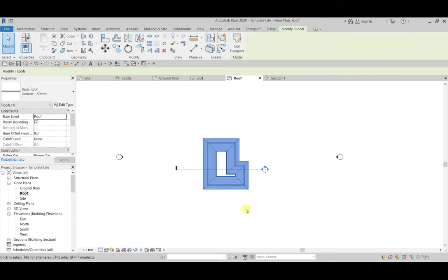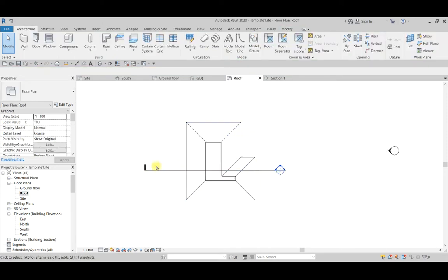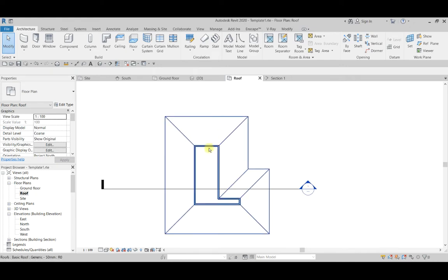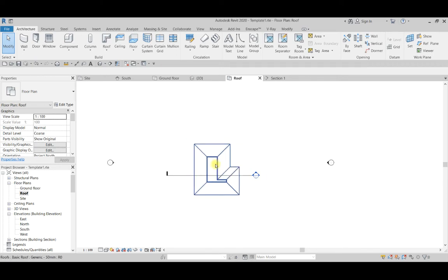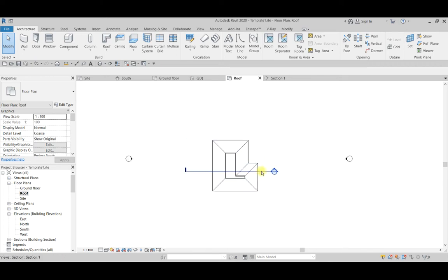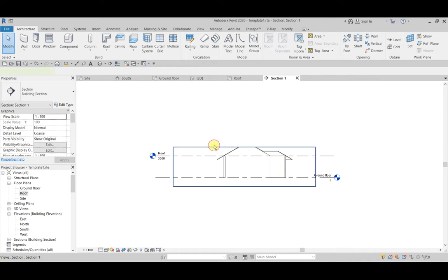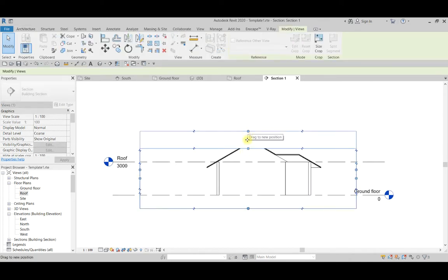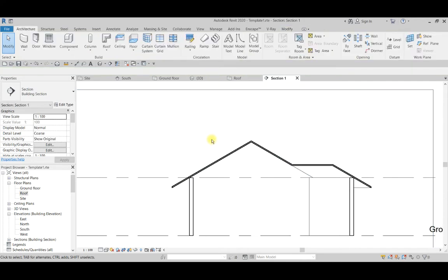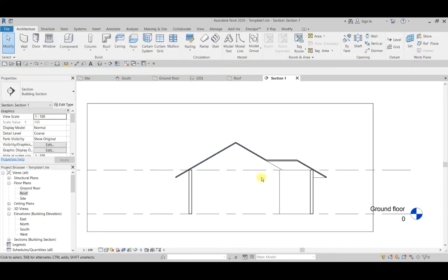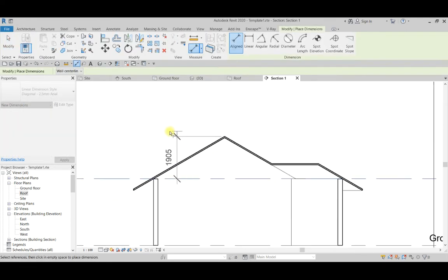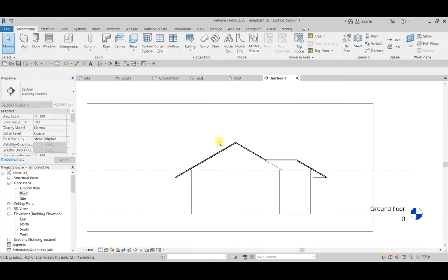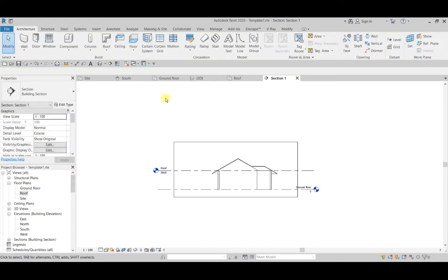on OK. So realize that the view range in which we are having has made a section through our roof, and we are not seeing the apex of the roof. So I'm going to give you an example to see how it works. So when I come here, before we can get the apex of the roof, we have to know the length or the height of our roof, which is 1.9. So the height of our roof is 1.9.